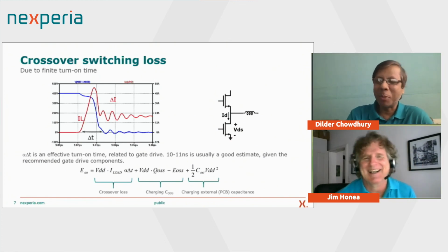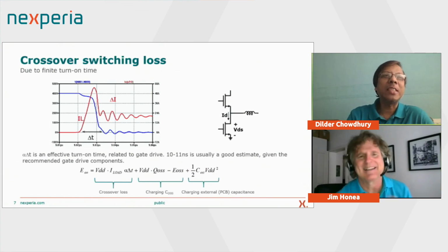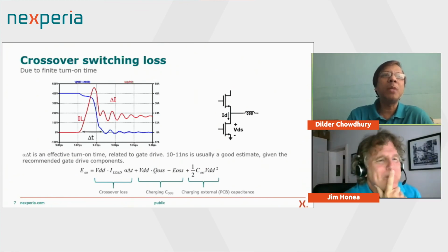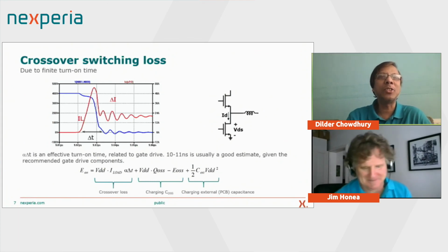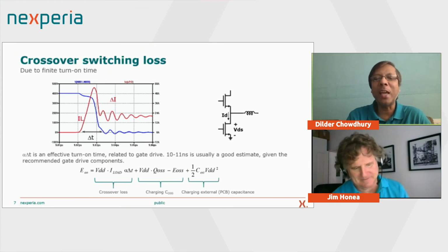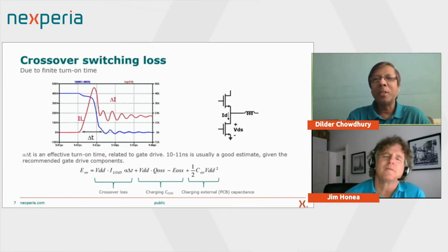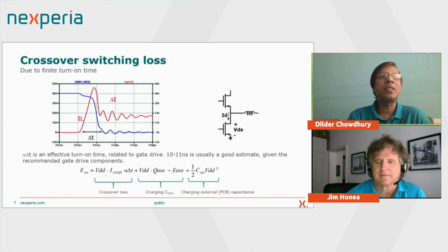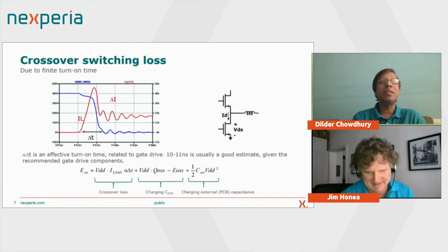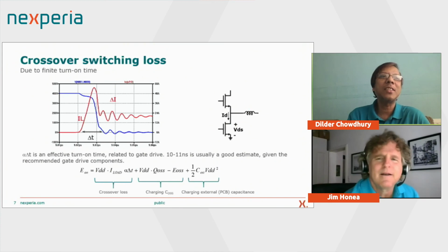On this one, in perfect condition, yes, but whether you'll be able to maintain it over the whole load area is the biggest challenge, because as soon as you have any load transition a little bit uneven, then you start causing that zero voltage switching to go into a non-sinusoidal form, and that's where some of the switching losses come in. Jim, you might be able to explain. It's a non-ideal part of the zero voltage switching when it can introduce some of the losses, right?